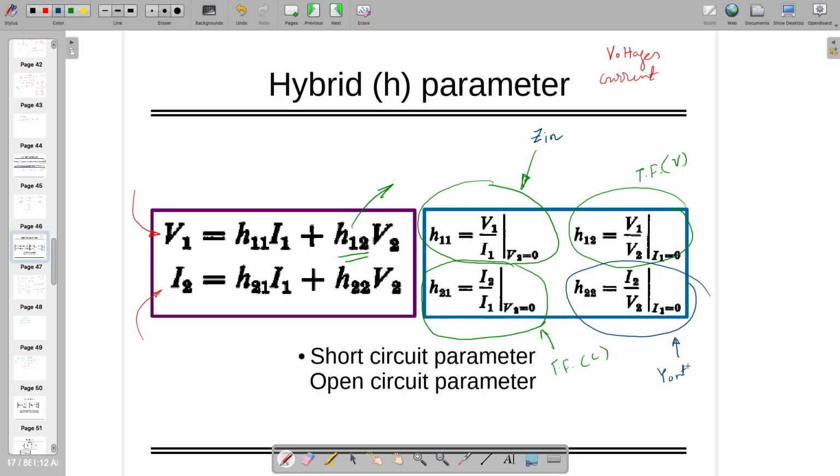So you can have all the information, because I wanted to know the input impedance, the output impedance, and the transfer functions, so that I can see the behavior of my circuit. That's why the H parameter was very popular, but afterwards people found that the Y parameter is much easier and handy to use. If you're reading old books written before 2000, you can see the H parameter is dominant, but the new books talk about Y parameters.